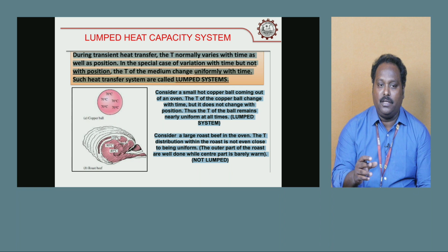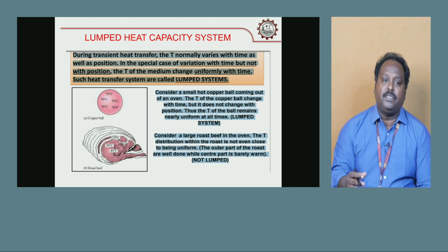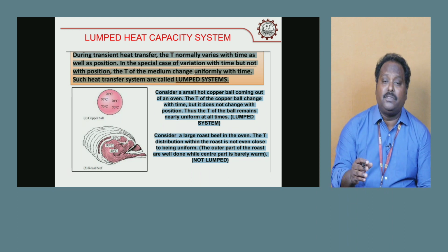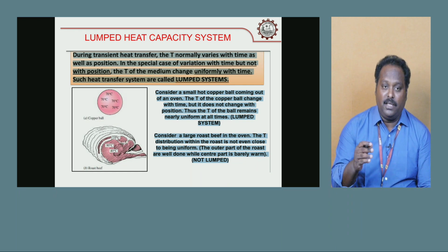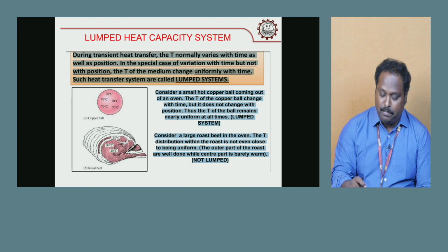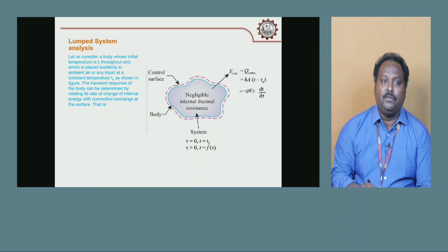But if you take a roasted beef, inside the temperature is 140 degrees centigrade, at another point 90 degrees, 110 degrees. The outer surface might be roasted properly, but inside it has not been roasted, so it cannot come under lumped system analysis. So you must understand the applications of the lumped system, and differentiate which is a lumped system and which is not. Now let us derive the governing equation for lumped system analysis.